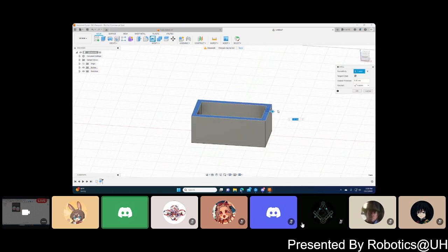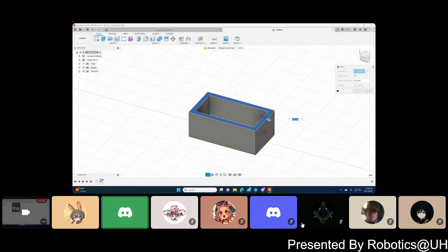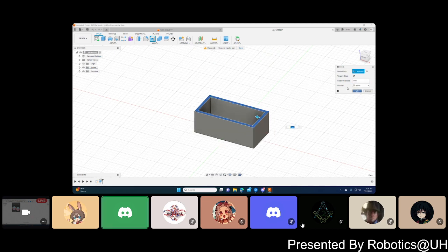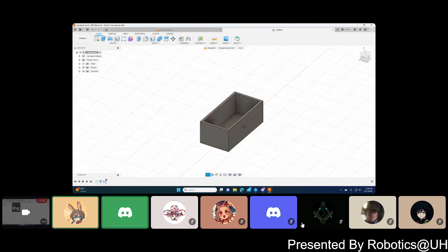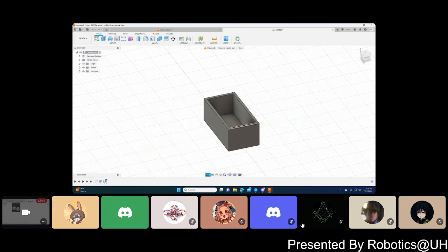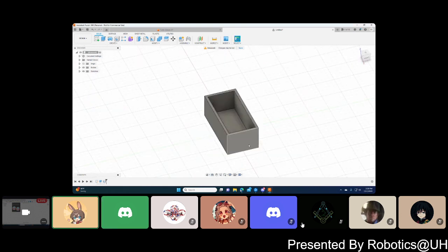Okay, so outside makes the shell outwards instead of going inwards. It's additive instead of subtractive. And both, we can infer what that means. So I'm gonna hit enter, and that gives us a box. On all sides, it's gonna be like 3 millimeters, right? All right.